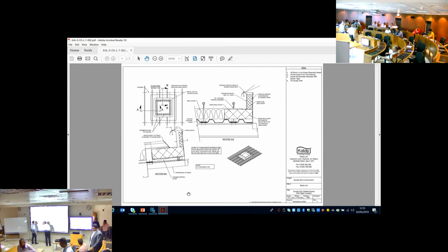That gap is 50 mil. And when it's installed, you need to make sure the quilt is soft insulation, so this bit can float. But sometimes at the corners it can crack because there's not enough room. The sheet wants to move at the sides, and it's cracked here.